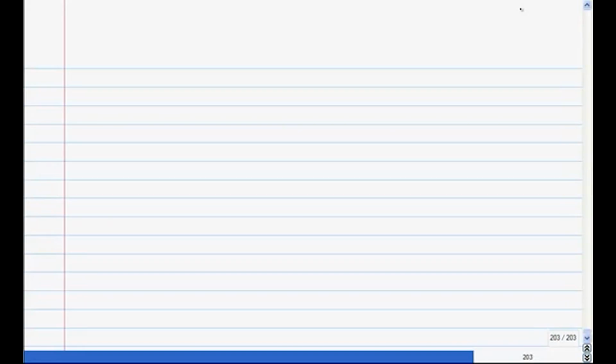We were in the business of finding the forced response of a linear system, in particular a first order RC circuit, to a sinusoidal signal, which can in general be represented as Vp cos(omega t plus phi). That's a sinusoid of frequency omega and some amplitude Vp.